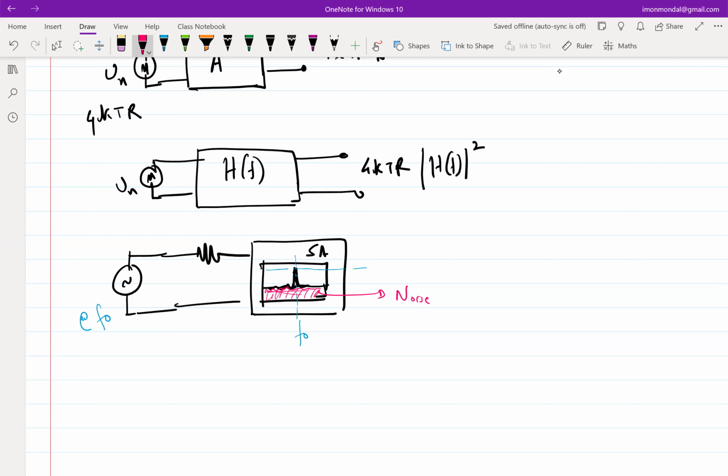Right. So power spectral density is the noise in 1 Hz bandwidth. If your bandwidth is 10 Hz, you'll have to integrate over 10 Hz. If your bandwidth is 1 kilohertz, you have to integrate over 1 kilohertz and so on. In one of the earlier classes, we saw that if you have a very wide bandwidth channel, you are going to accumulate a lot of noise because effectively it gets multiplied by the bandwidth, right?